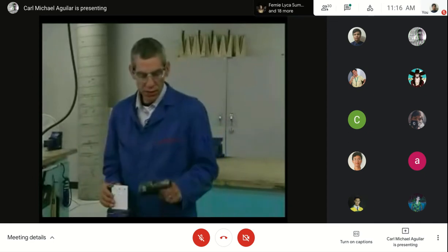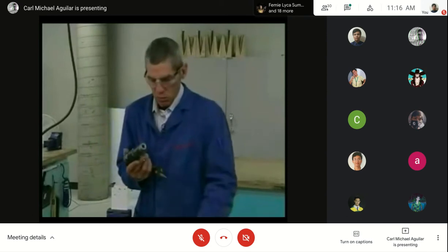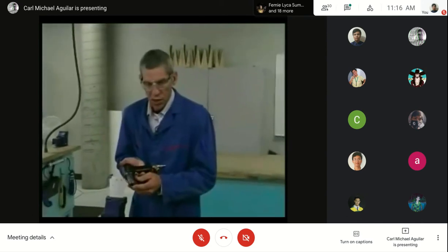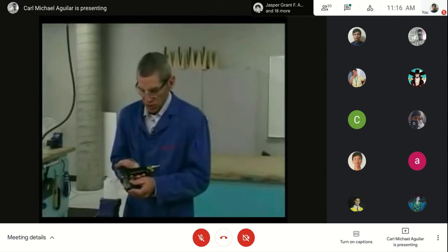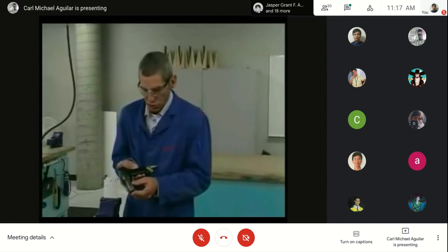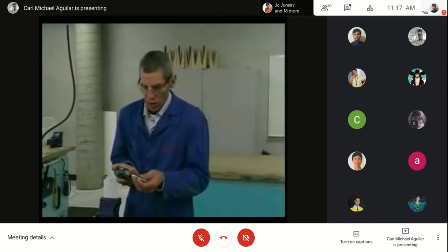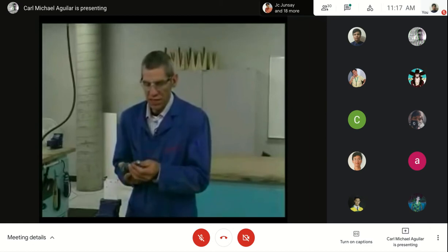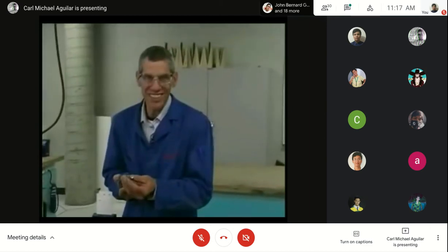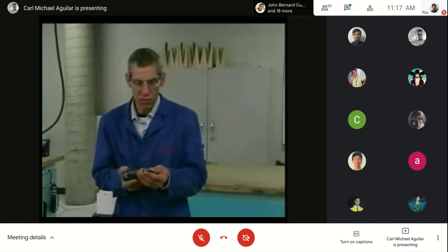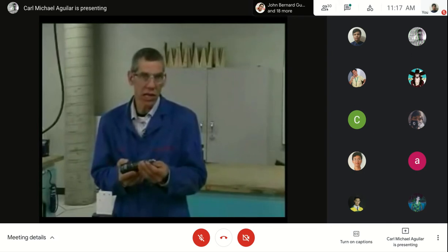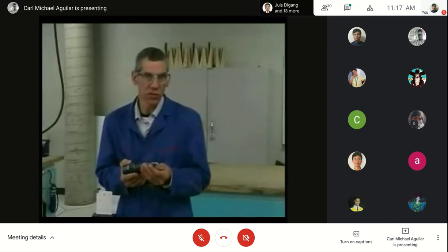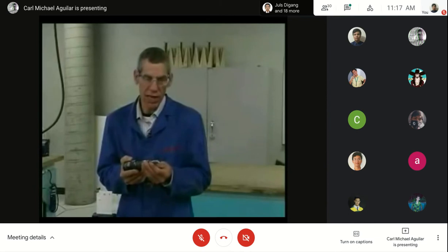Setting the rivet gun: rivet guns come in light and heavy hitting styles. Ours is a 3X gun. We'll insert the rivet set in it, ensuring that I have the correct set. For our purposes, I'm installing a 5/32 MS20470 AD5 diameter rivet.